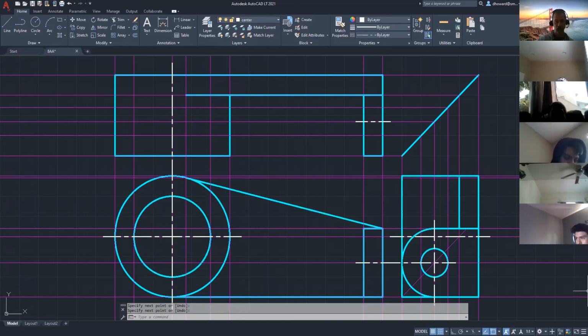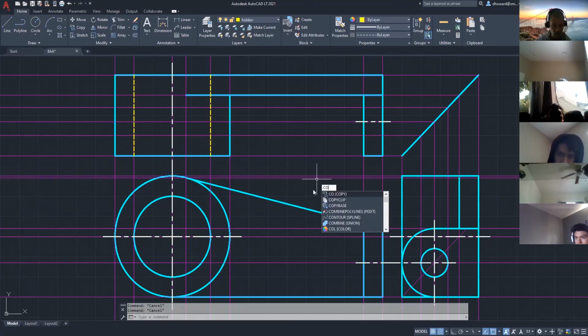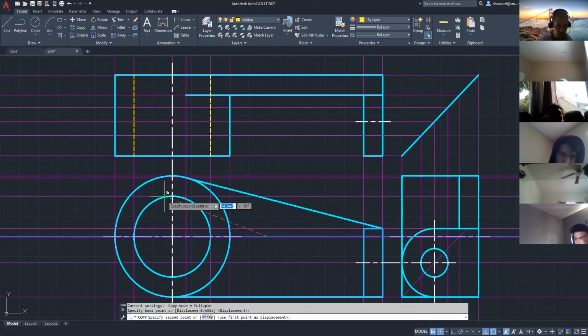And now we'll do the hidden lines. Go to my hidden layer. We can start off with the big one here. So its edges in the top view are seen from there to there. And its edges in the right side view, well, I'm missing some construction lines, so I better put those construction lines in here. Let me grab those. I need one there, I need one there.